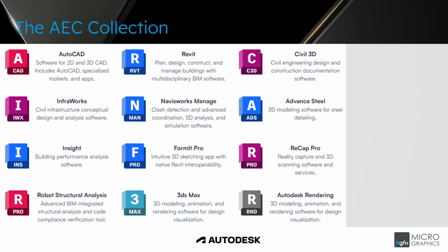But Revit is also incredibly, I don't want to say friendly, because I feel like that can be misleading in some senses, but Revit models can be integrated with a lot of different packages, which we will chat about a bit later. If you're looking within civil engineering, this is your structural modeling package. You can model steel structures. You can model concrete structures. You can do your rebar in there. There's been incredible improvements to the rebar functionality as well. And of course, we've developed ways to schedule that rebar accurately, especially in accordance with the South African code.